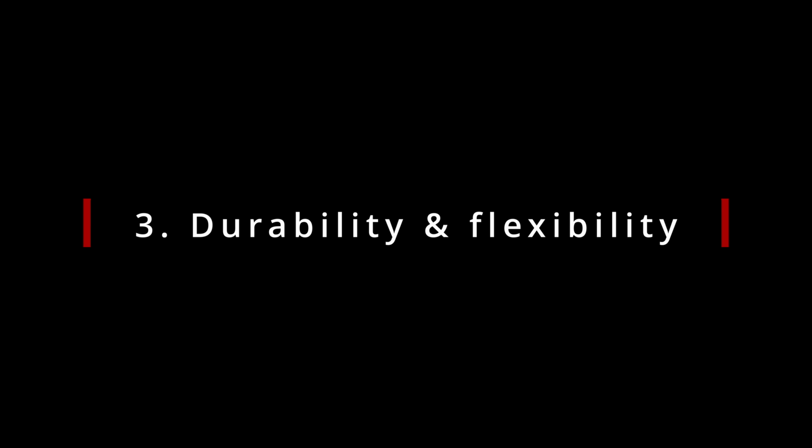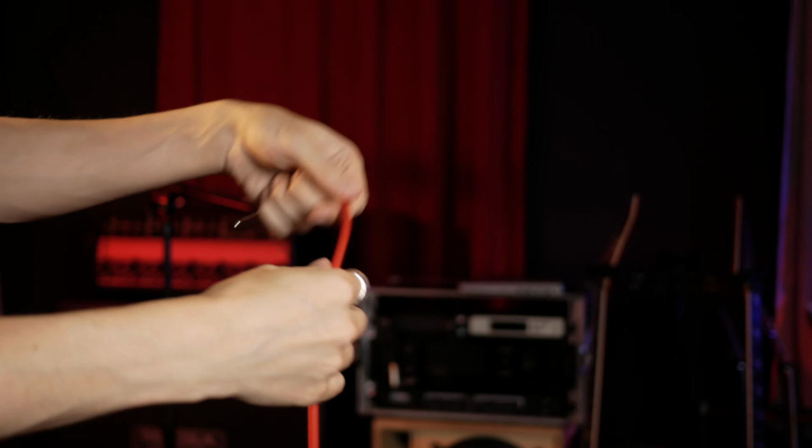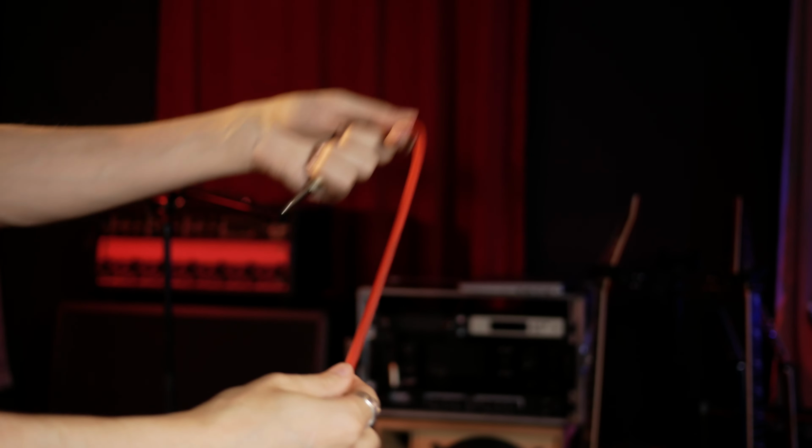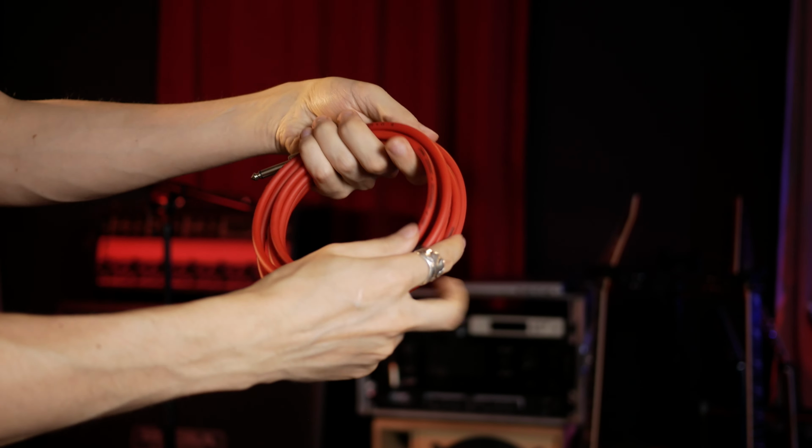Third, the durability and flexibility. This relates to the previous one, but now we are focusing only on mechanical aspects of the cable. As you know, microphone cables are filled with cloth fibers, which in combination with thick overall insulation makes them flexible and durable. In case of multi-core cables, handling of a multi-core cable can be a real pain, and we want to avoid not working channels. So it's very important to know if the cable should be installed or used every day.